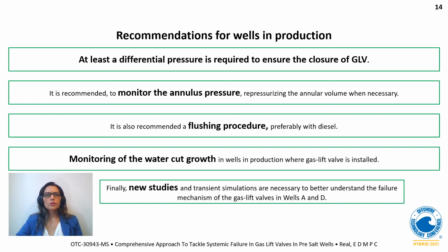Monitor the water cut in wells with gas lift valves. It's important to ensure a high dosage of scale inhibitor. An improvement in the chemical injection system would bring great gains to the integrity of gas lift valves and other equipment. New studies and transient simulation are necessary to better understand the failure mechanism of the gas lift valves in wells A and D.